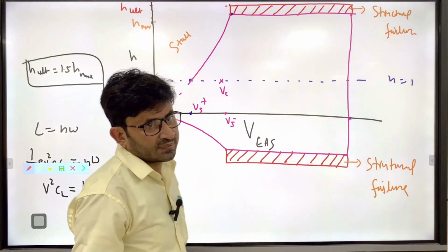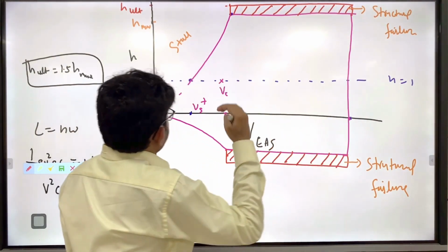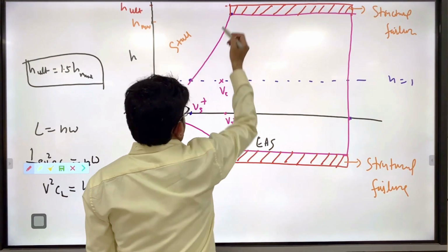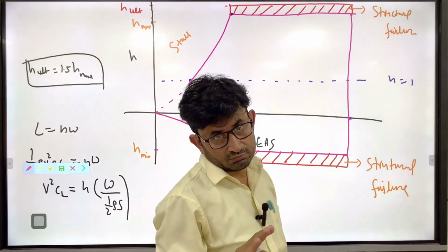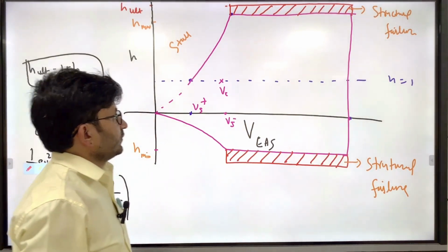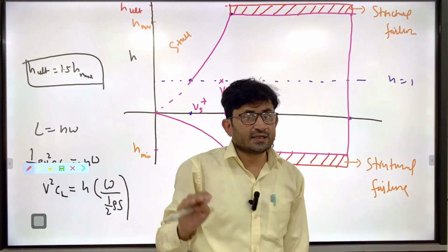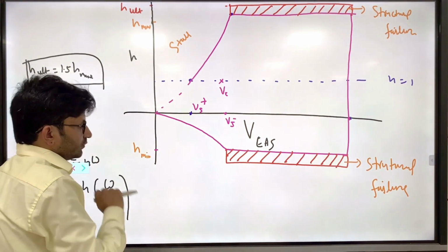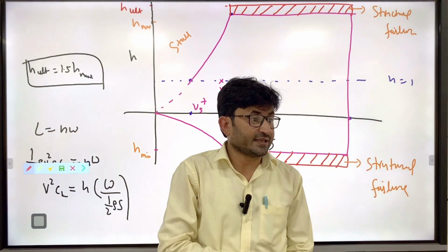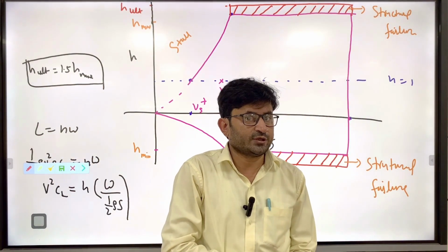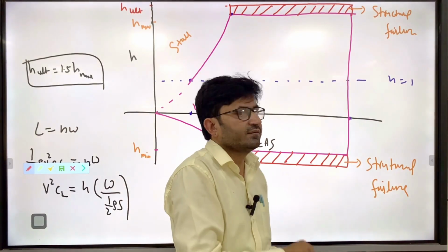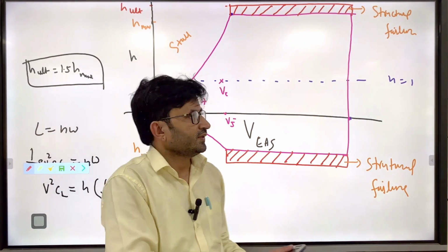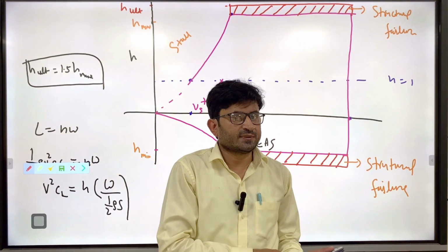Why have I taken the two examples? Because if your aircraft is very light, 10 kg, 20 kg, there is a good chance that you will go out of the envelope if you have a gust. But if you have a commercial aircraft, the gust will affect it less. One is a UAV, another one is a commercial aircraft. The light UAV is more sensitive to gust, and we have already seen with the example how the delta n value comes out, and also for the commercial case.